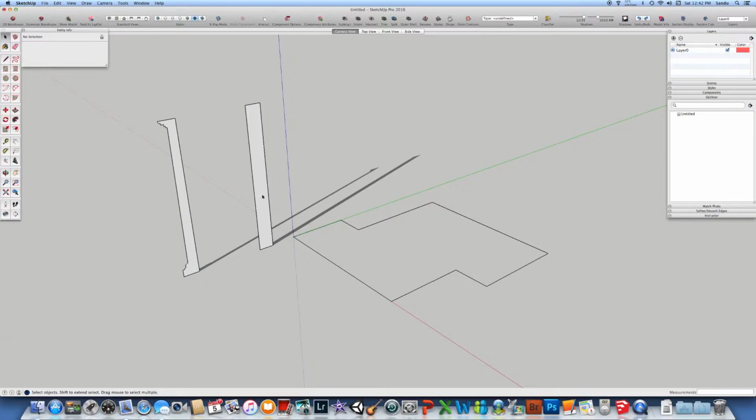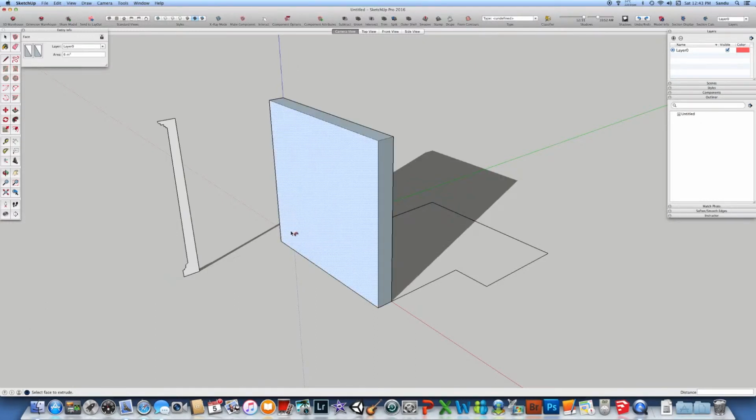So basically, if we want to follow this line here and we want to create a wall with a certain height, we can have the section of that particular wall, and we can move that section right to the point of the outside of the line. So basically this is an interior perimeter of the wall, and we click on the push-pull tool, which is this one here, and with that face selected, if you just give the click, you're gonna see it's gonna take only a line.